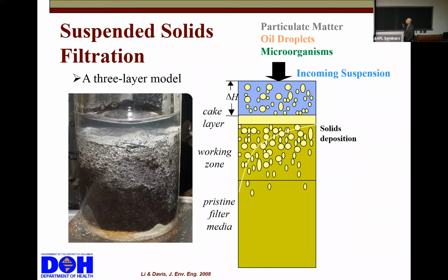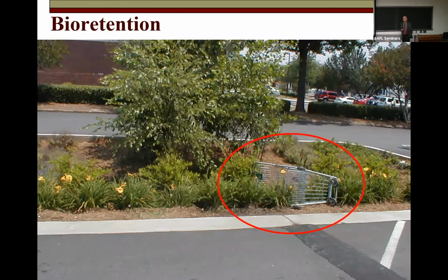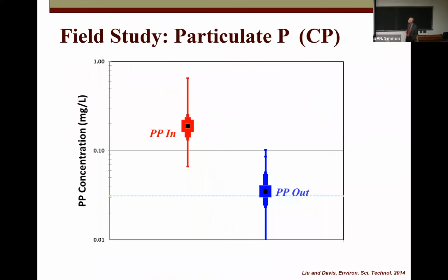And again, we look at this, and really it's almost independent of the media. You can put a very sandy media in, you can put a very fine media in, you're still going to get very good removal of suspended solids and anything particulate related, oil droplets, microorganisms to a certain extent. The capture is part of the story. With microorganisms, what happens after the capture is another story, and that's not a story for today. They also capture big particles. We've all seen that. If you go out to these systems, they're always full of bottles and so forth. They'll capture anything and won't let it go through. So they capture suspended solids.